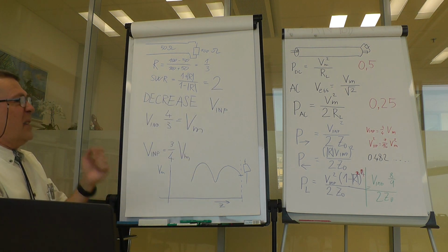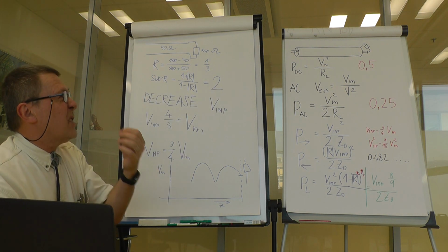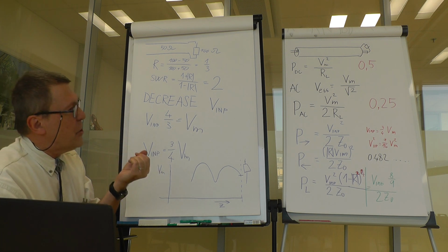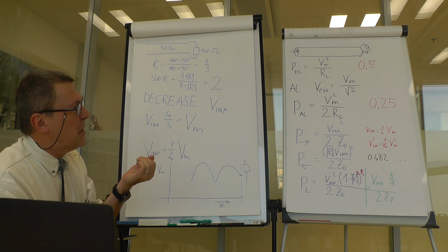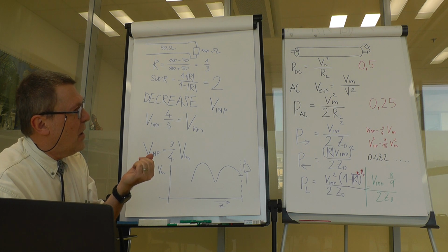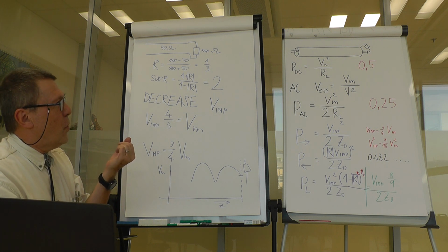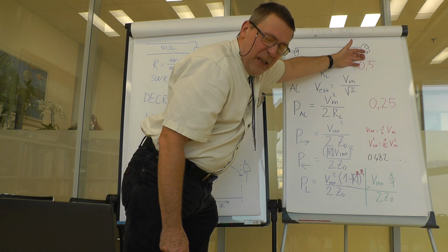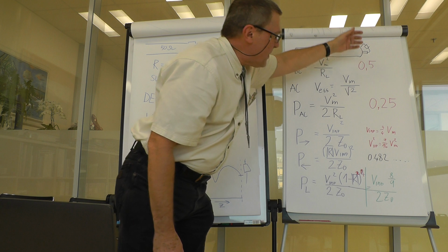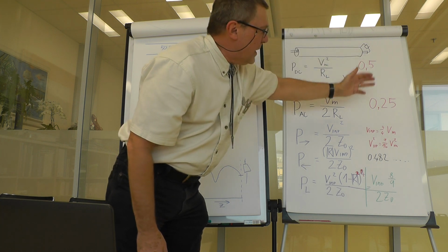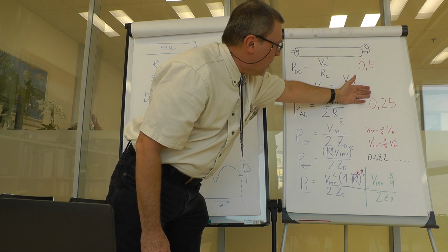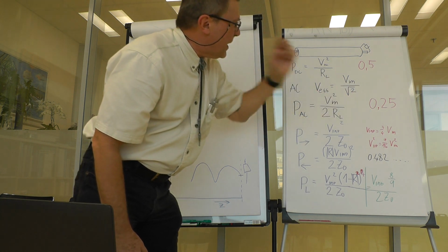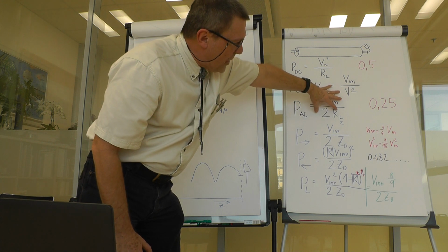considering standing wave effects. So this comes to a fact that the original cable could deliver one-half of the power to the load if the impedance increased twice, but would be anyway only 1/4 of the power delivered to a matched load.